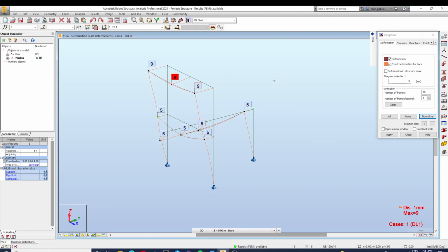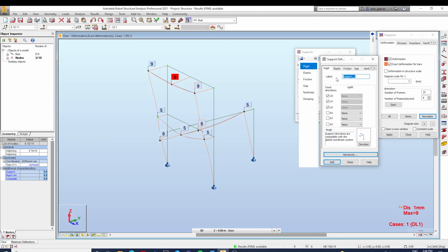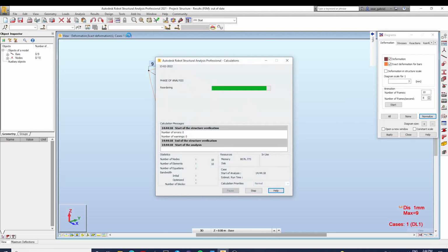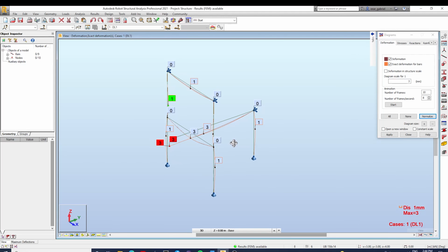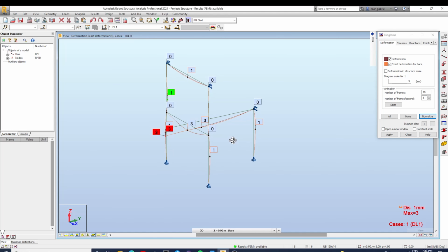As we mentioned before, the structure is leaning towards the y-axis. So if you have some other structure bracing these columns, you could add a roller support restraining y direction, and that would give you more realistic displacements. So here I applied supports restraining y-axis movement, and that 5 millimeter displacement is gone. On the other hand, if you don't have anything bracing and preventing the frame to tip over, you might need to keep these displacements as small as practicable.